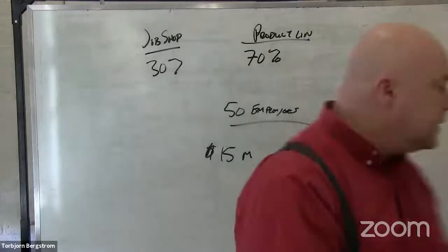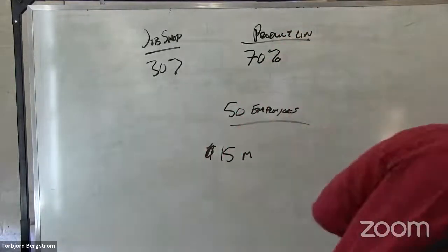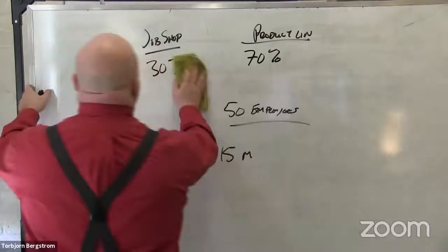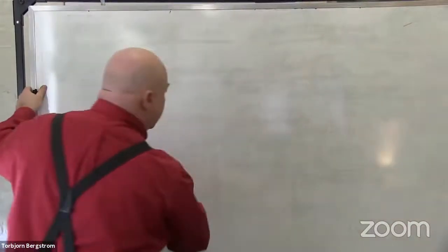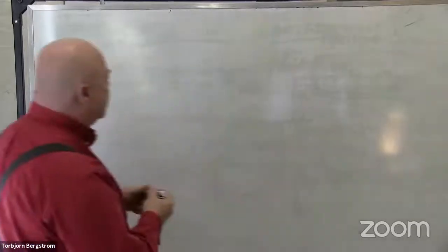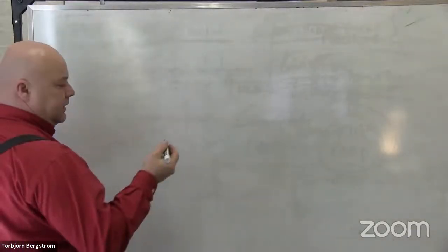You could automate transportation to and from the production lines to the warehouse, because if you have someone driving a forklift, they aren't really adding any value to the part. So you could automate that and save money there. All right, so there are sort of categories of things that we could automate. And I think it was a tough question because you don't have enough information to decide.